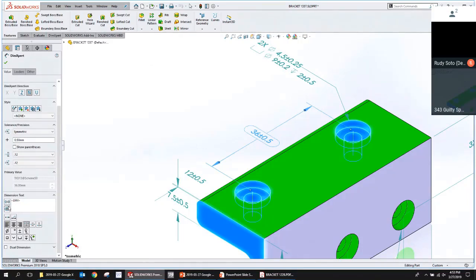I think my answer to that is it depends on the company. There definitely could be companies that don't use it at all, but if you're subbing out a lot of your work, it could be beneficial to the manufacturing team to be able to rotate the model, zoom in and out, and take sections. If they're wondering what's actually going on here, you can section in that 3D PDF. So there's benefits to it. Is it a requirement though? I don't think so. All that information is captured in the STEP file.